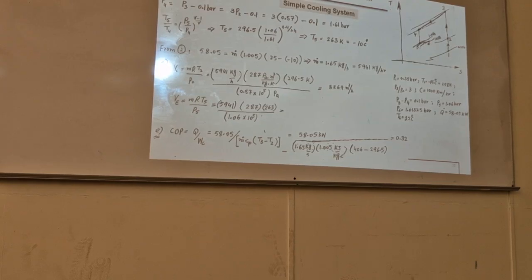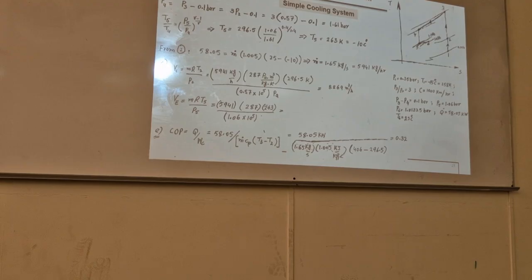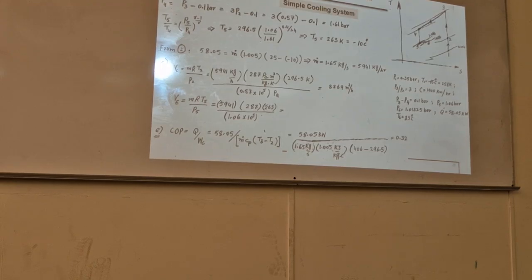Of course, volume is changing from inlet to outlet for both. So I will go for the maximum volume handled, because you will design this turbine from inlet to outlet, where volume is increasing. You should know the maximum volume so that you will make the turbine structure accordingly.